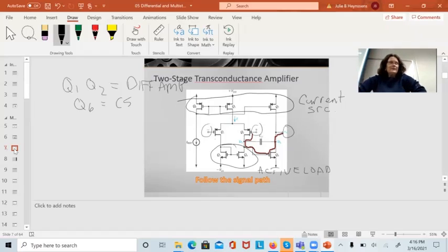The capacitor's in there on purpose. It is called, and this is something we'll talk about after exam 2, a compensation cap. What this does is, this whole circuit right here has a huge mess of poles and zeros in it, that generates a Bode plot that I'd be proud of if you could do in 280. It's the 280 like Bode plots, right?